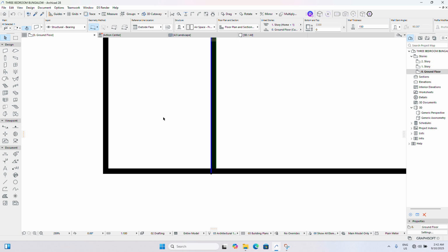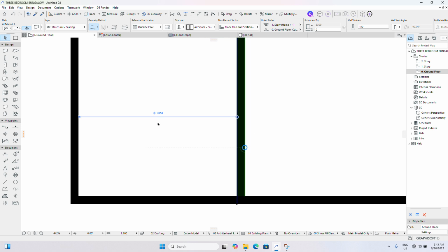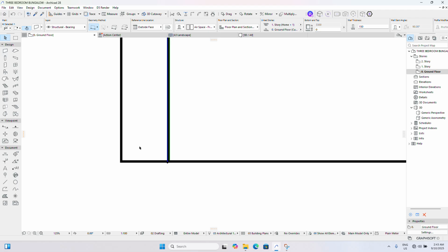If you don't add your wall thickness, even if it's 225, if you don't add the 225 to any dimension you want to offset, it will minus the wall thickness from the figure you typed in on that distance. So that's another thing you need to note.